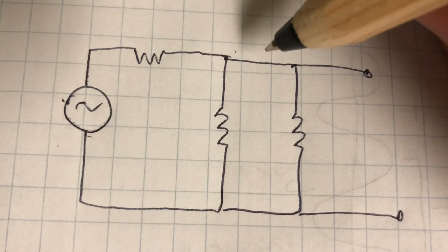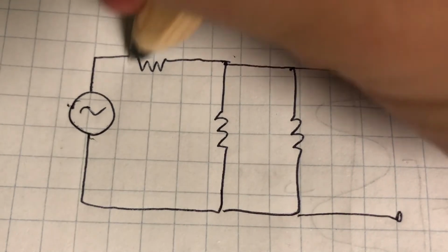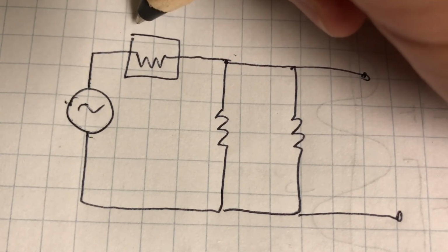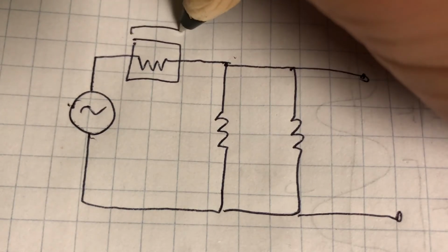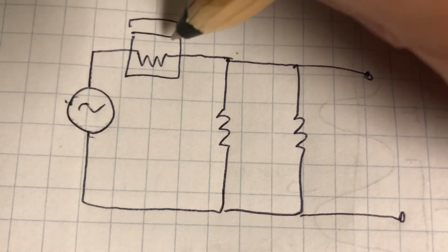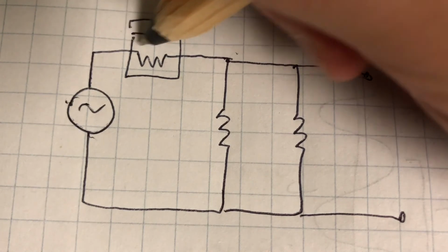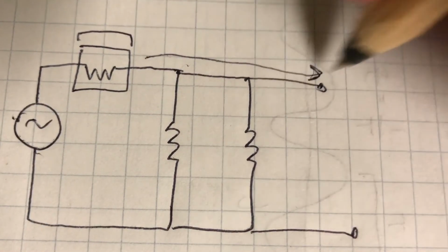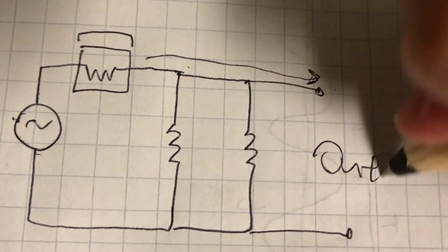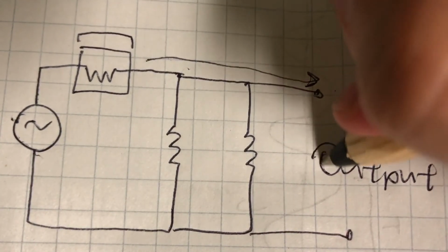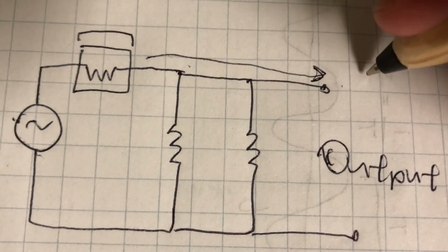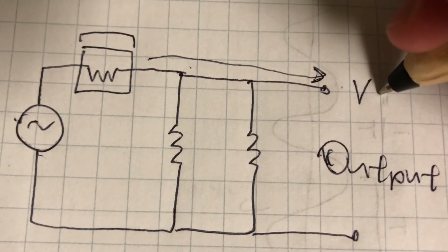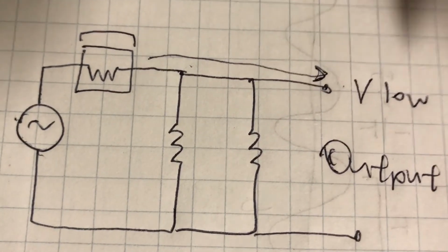And when we have a high current, we can look over here at the source resistor, it means that there's going to be a greater drop in voltage between these two positions. So because this voltage drop is big, by the time we get all the way over here to the output, our output source is not going to get any voltage. Well, not any, but it's going to get a very low voltage. Okay, so V over here is very low.